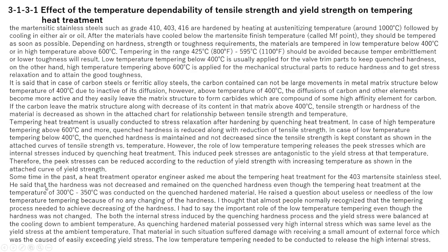He said that the hardness was not decreased and remained at the quenched hardness even though tempering at 300 to 350 degrees Celsius was conducted on the quenched hardened material.